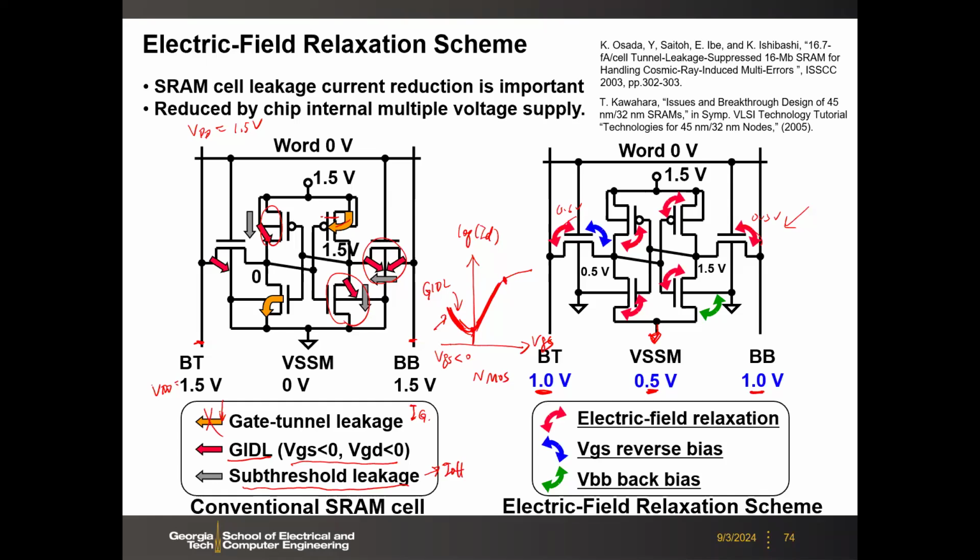Is it more common to bring VSS up or VDD down? So you can bring the VSS up, I think. Is this being considered as a dynamic voltage scaling? No, this is not your logic chip. You have the DVFS. So here is just in the memory hold condition, you have different bias condition.